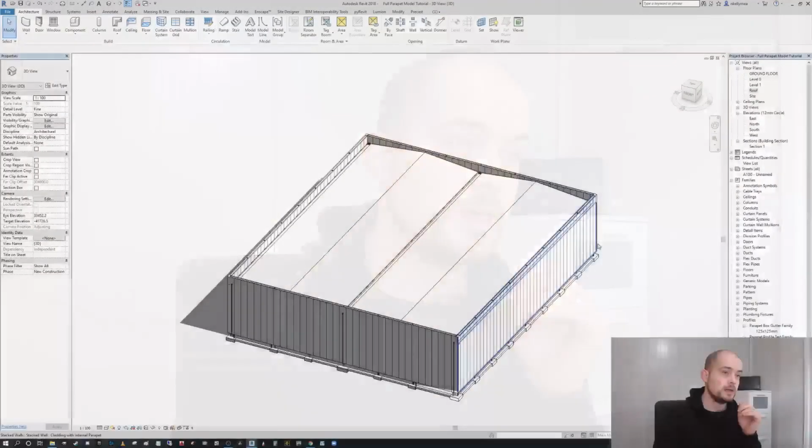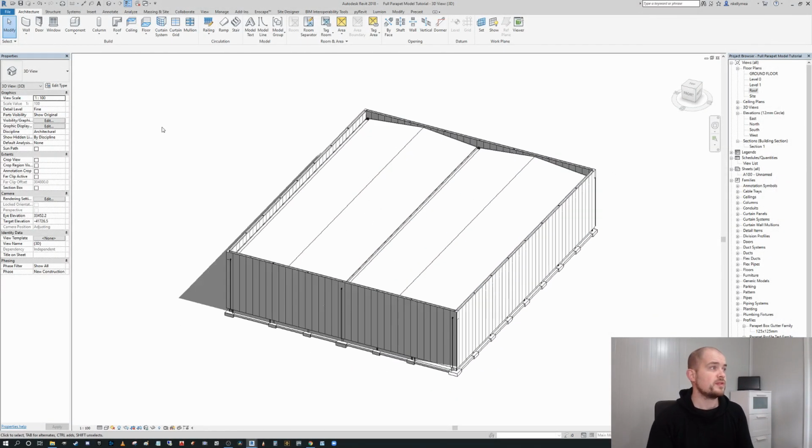Okay, so what we can do is we can apply the parapet capping to the wall construction, the wall assembly, as a profile, a sweep on top. Okay, or we can do it as an in-place component. Okay, in this exercise, what I recommend is you go and watch that video in full if you want to get into the nitty-gritty, but in this exercise I'm going to show you both methods, because I'm going to do the in-place component for the insulation, and then I'm going to actually apply our parapet capping to our wall assembly here as well.